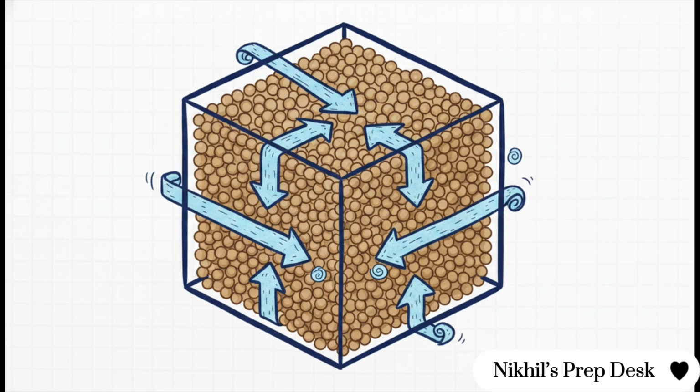It moves in 3 dimensions. Luckily, Darcy's law gracefully scales right up to 3D by combining the partial derivatives of the flow along the x, y, and z axis. And here's a really cool part. If the soil is isotropic, meaning it behaves the exact same way in all directions, these 3D equations beautifully simplify our calculations. We can just factor out a single hydraulic conductivity value for the entire mathematical model.